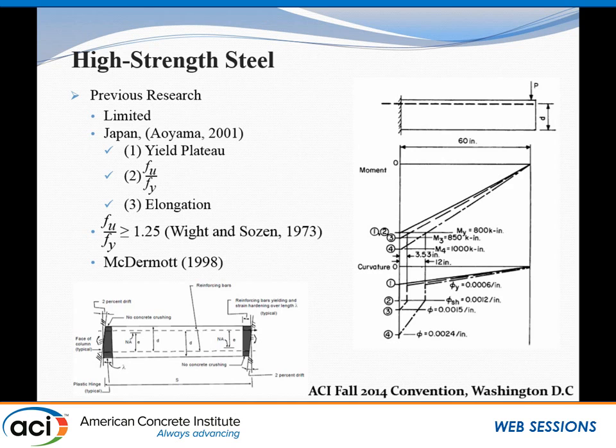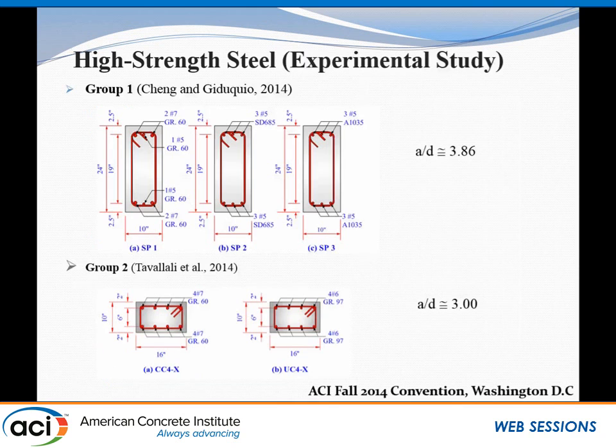He further suggests that we need to specify a minimum elongation strength for the flexural reinforcement of at least 10%. So, the experimental results of two previous studies are collected here to evaluate the design recommendations I just addressed.